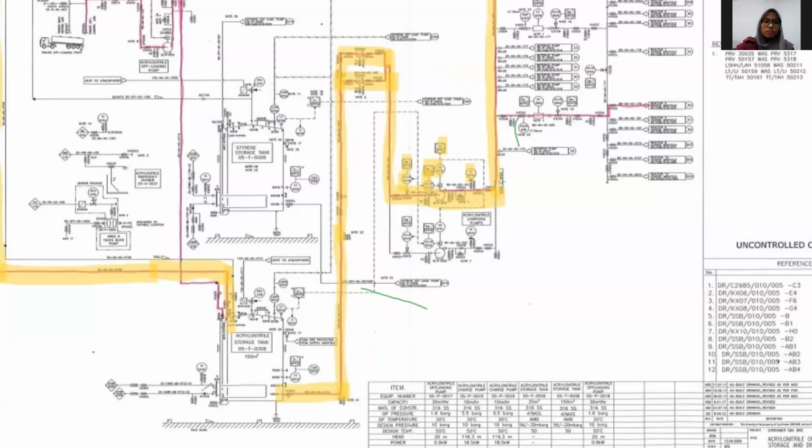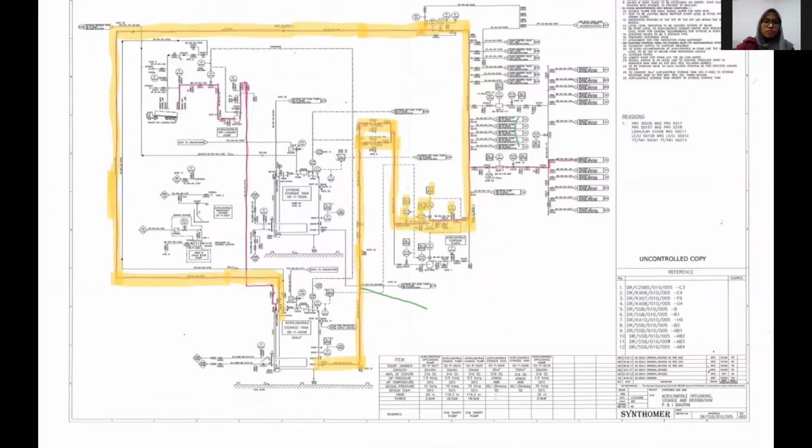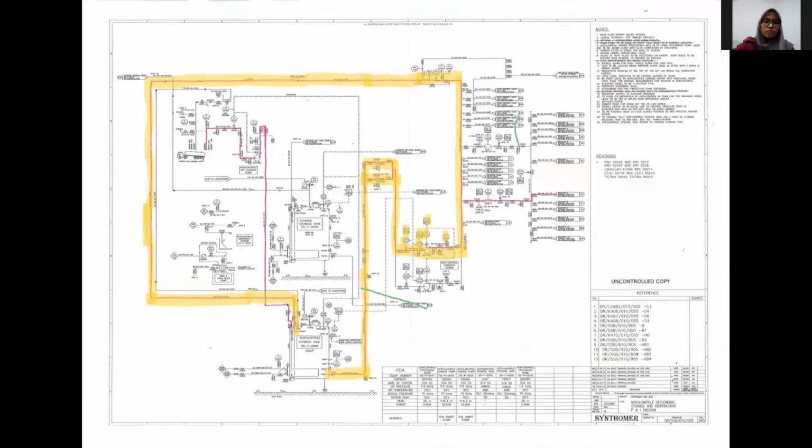Okay, then after 6 hours, the citric acid supply and also the steam have to be stopped, and then drain the second wastewater into the wastewater plant. We have to flush the tank with nitrogen gas to ensure the tank is dry, remove the remaining acid in the tank, and close all the valves.